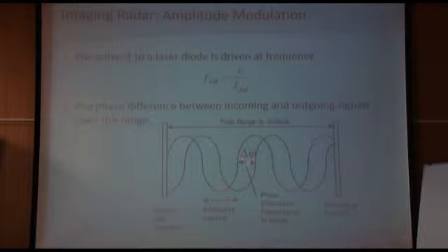If you see here, this will be the emitted wave, and this is the reflected. You have an ambiguity interval, because if the distance is too far away, you never know whether this corresponding wave is this one or that one, and that's why you have an ambiguity interval of a certain range. Usually for these scanners, this is approximately 60 meters. So you can measure in a range of 60 meters before this ambiguity interval is there.